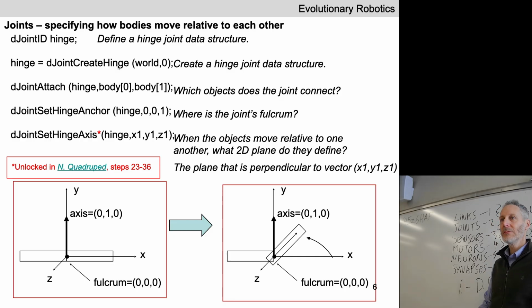What about your shoulder? What does that make possible? Now you got to think about the degrees of freedom of your upper arm relative to your torso. How does your shoulder constrain the relative motions and the relative orientations of your arm relative to your torso? Does it do the same thing as your elbow joint and your knee joint? Does it remove all 3 positional degrees of freedom and 2 of the 3 rotational degrees? It removes your positional freedom, but you can still yaw, pitch, and roll. It removes positional independence.